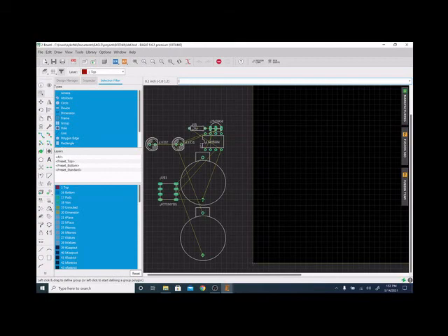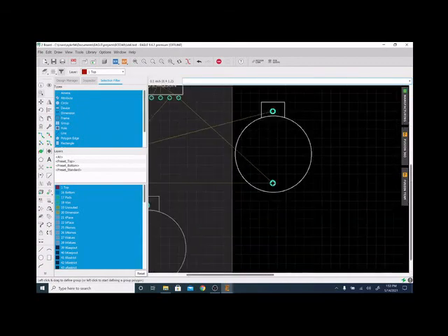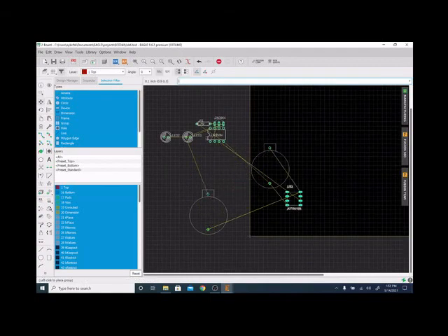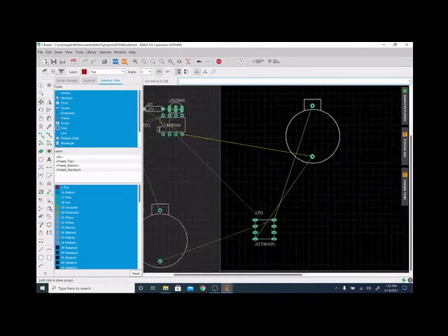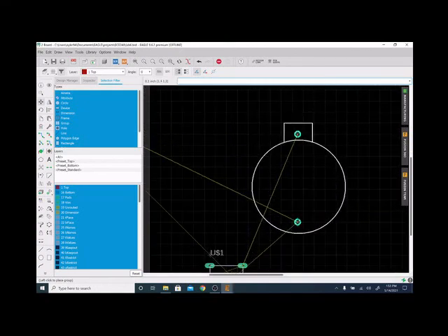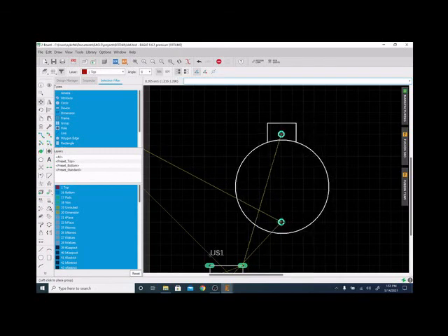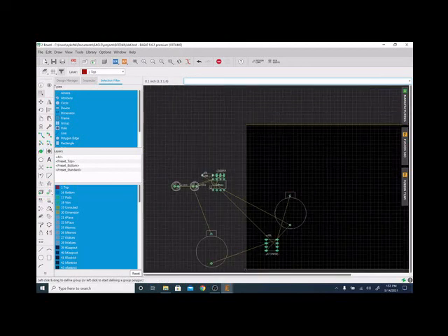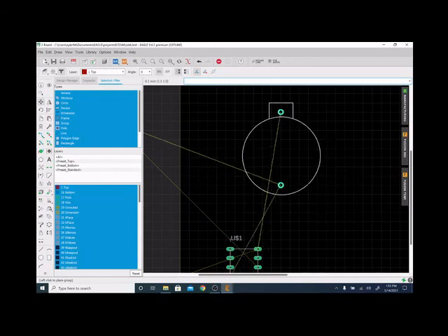What the alternate grid does is, if you notice, if I drag this battery, and in order to click a component, you have to select its anchor point, which sometimes can be hard to grab. It's that little crosshair. That's why I always like to put it in the same spot every time, that bottom left corner. So when I move this component around, you can see it only moves according to each grid. I mean, that could be really, really annoying, especially if you need to do finer motion. So what I'm going to do is hold that Alt key, and now it goes to my alternate grid. And so then I can place it exactly on those crosshairs, and I'm not worried about trying to fuss with that. But now if I'm not holding the Alt key, it'll let me go back to my gross movement.